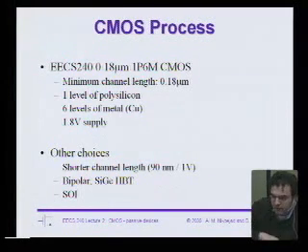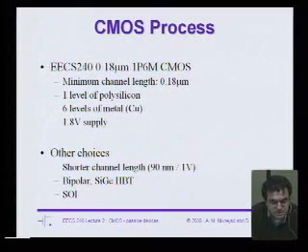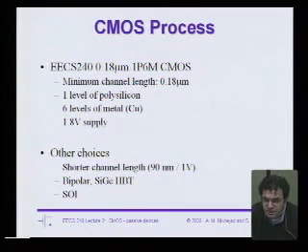Okay, the process that we have available to us is the 0.18 process. It's a single poly, 6 metal level process. It's a fictional process. There's an issue with having access to a real process, as I discussed last lecture, but we really have the next best thing here. On the Moses website, there's run-to-run process data for a 0.18 process from TSMC. Professor Peter Kinget has put together a fictional model that tracks the variations in that process. So it should be pretty accurate in the sense that it represents a true analog process that you may use. But of course, it's a fictional process, so don't expect that you can just take your design and port it over to TSMC 0.18 and start making money.